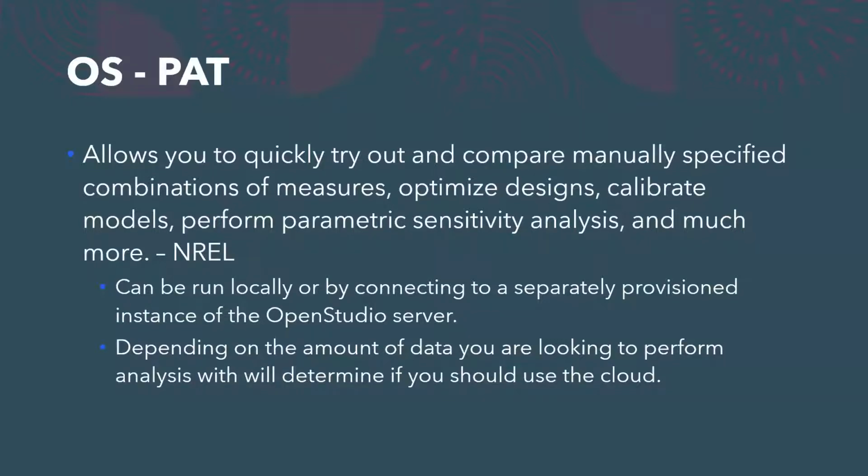And there's actually two separate features. There's a manual specified mode, as I said here. There's also an algorithmic mode. The algorithmic mode is if you're going to be doing simulations like over 50. So we're talking about getting into the couple hundreds of simulations, and that's definitely going to require you to use the cloud. Typically, you should be running anywhere from 5 simulations to 20 to 25. And depending on what your hardware is, you should be able to stay locally.